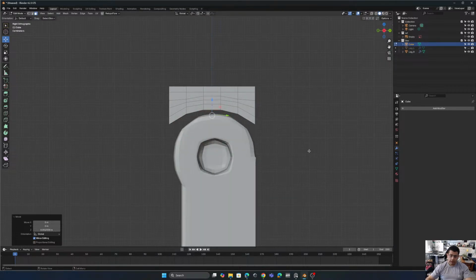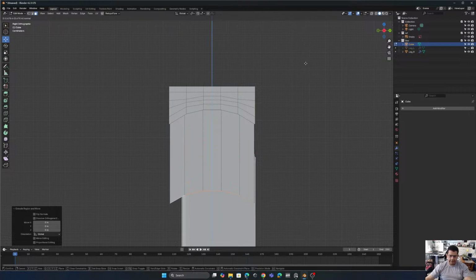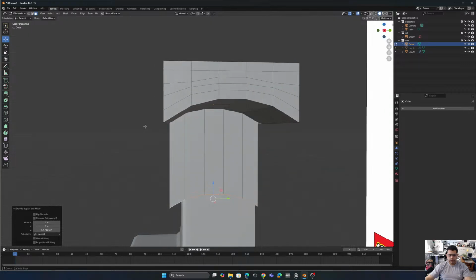So we're gonna press 3 to see the side, and now I'm gonna press E to extrude this. It's already in the Z axis. As you can see, the blue line in the middle says that it's already active, so we're only gonna move here, and it's not gonna be affected by the Y or X axis. So we're gonna go straight to cover the whole circle that's on the leg. And when we already pass that part, we're gonna click, and it's gonna end the extrusion.